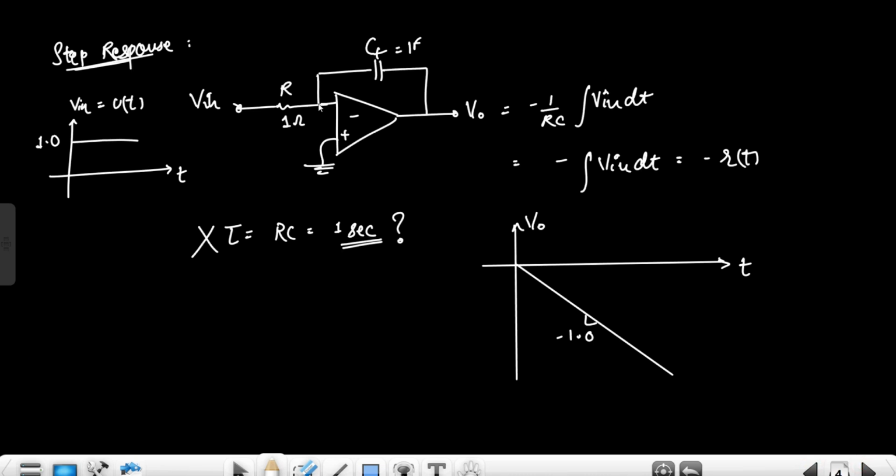And let's see from other perspectives. Let's say here this is the 0 volt, so whatever current flows in this resistor simply goes into this capacitor, and this current is Vin upon R. So for all time it is a constant current, right? Whether the input is sinusoidal or a pulse input, the current will be constant. Whenever constant current flows through the capacitor, the capacitor goes into linear charging mode, which I have already discussed in the previous videos.